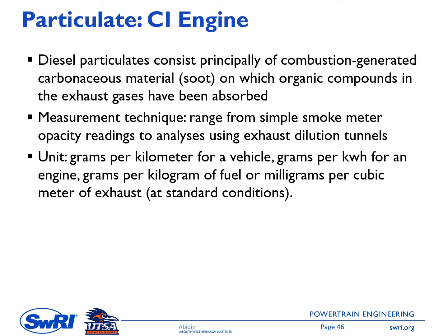For the diesel engines, particulates consist principally of combustion-generated carbonaceous material or soot, on which organic compounds in the exhaust gases have been absorbed. For the measurement technique, we can use a simple smoke meter or an advanced system using a dilution tunnel. The unit of this particulate can be grams per kilogram for a vehicle, or gram per kilowatt hour for an engine, or gram per kilogram of fuel, or milligram per cubic meter of exhaust at the standard condition.